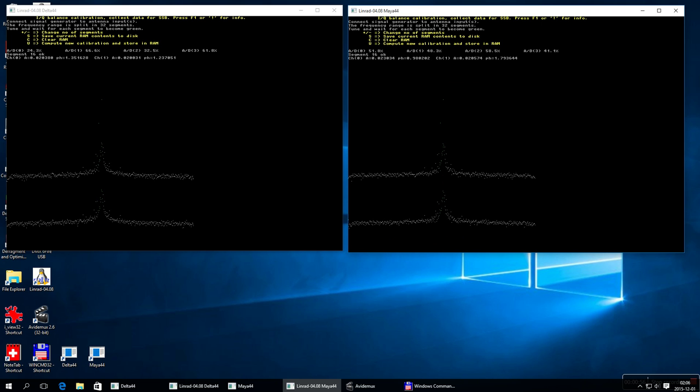And then change the number of segments, which is now 32, and I increase that to 64, and the same here, and that fits to the 1.5 kHz stepping that I'm going to do. So now I'll do the stepping, and I will come back when it's finished.